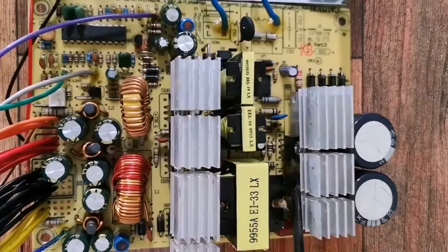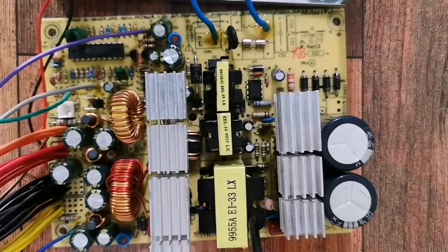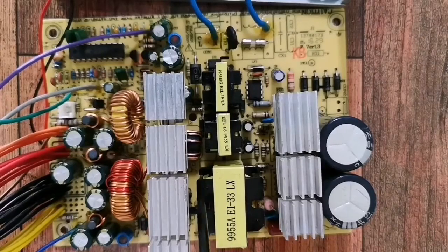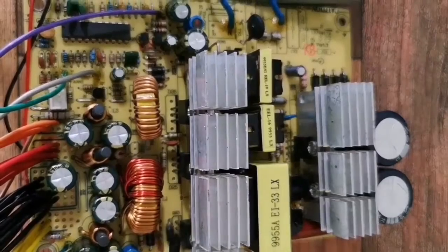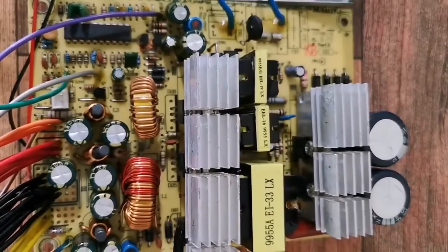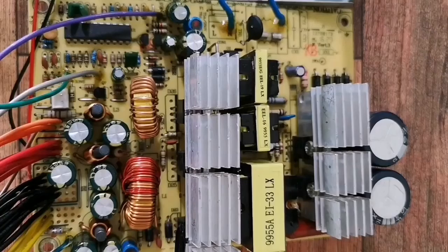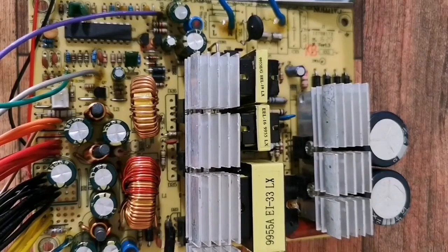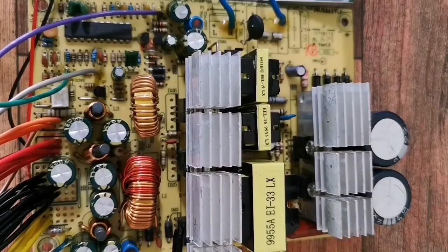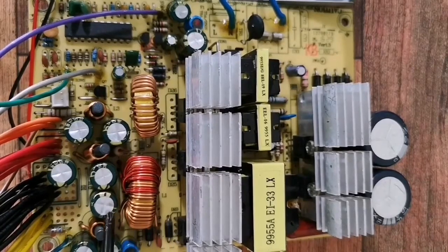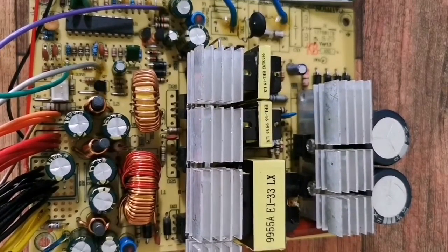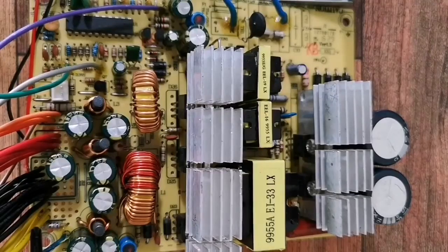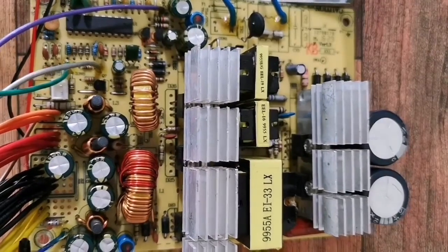The transistors will switch the big transformer, which is having 3 output windings. The first one generates the 12 volt part, which is rectified by the common cathode rectifier, and then the output through the coil will be smoothed by the electrolytic capacitors, and here we get the final 12 volt DC through the yellow cable.